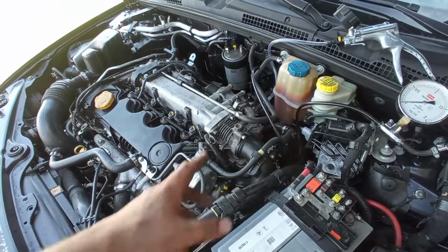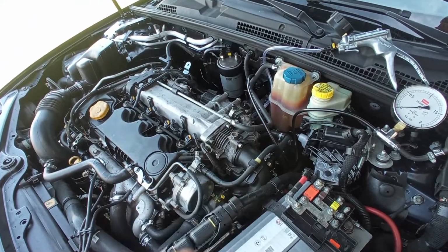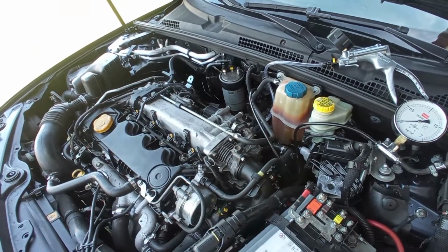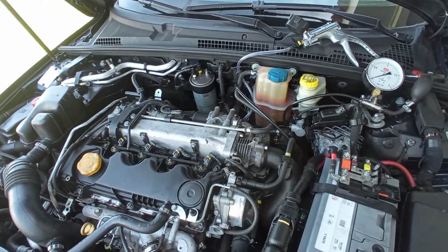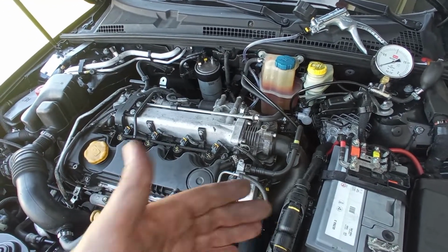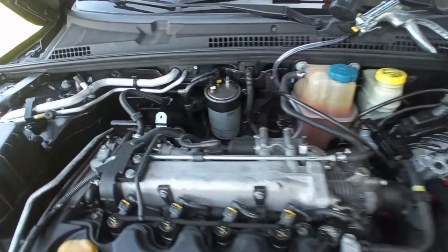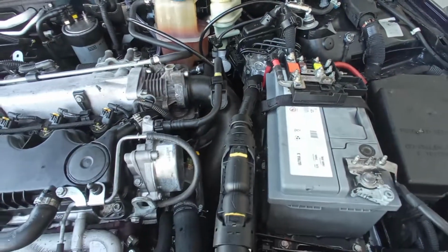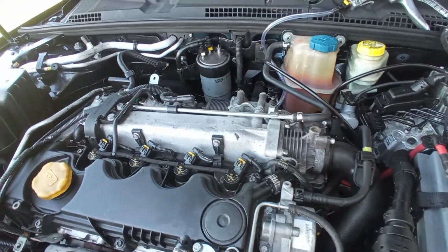everything is great. Now about here, this intake throttle body has the same problem, or I have an issue with the remap or wiring, because it has the same symptom, does not work. Maybe I have to check with the remap guys if I have an original map on this and go from there, because wiring on these cars is not a big issue, because the wires for it are going through here, there and all around the engine, and normally they do not fail. But yeah, I have to check that also.